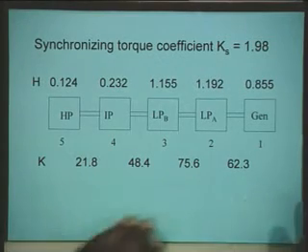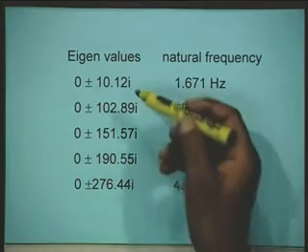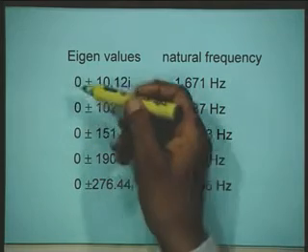Okay. Now, for this system we develop the dynamic model and determine the A matrix of the system. Now, in order to simplify our understanding, we neglect here the damping coefficients associated with the system. Right. When you neglect the damping coefficients and we obtain the eigenvalues of the system matrix, this system matrix A which I have just now shown is a real matrix, right, and since we have assumed the damping associated with these masses as negligible, with this assumption the eigenvalues come out to be all complex conjugate and the real part is 0.